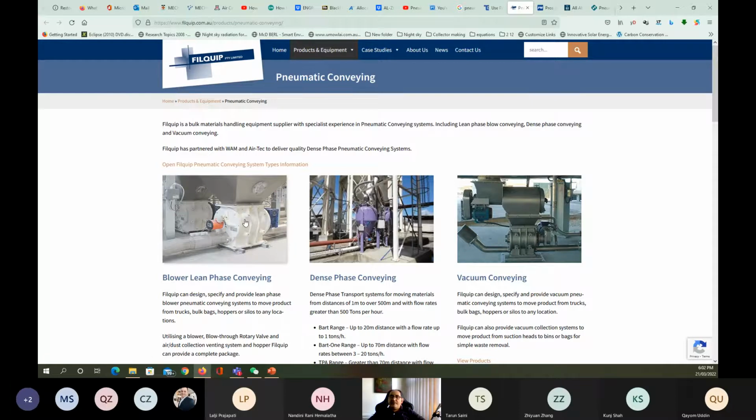For example, we have a device called the feeder. This feeder is going to submit the material into the conveying system in batches. I'm going to show you how it works. The blade we have inside looks like a star. If you cut it from the side, it's going to look like a star. It has a long length along the square outlet of the hopper, and starts to submit the material batch by batch, which is going to run through the pipe to the silo.